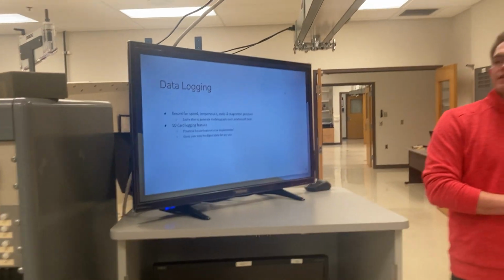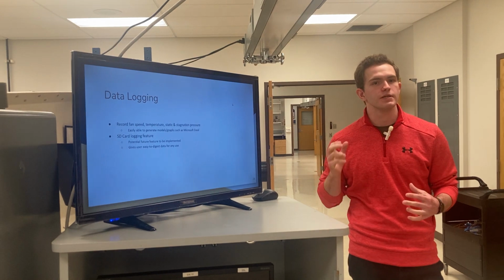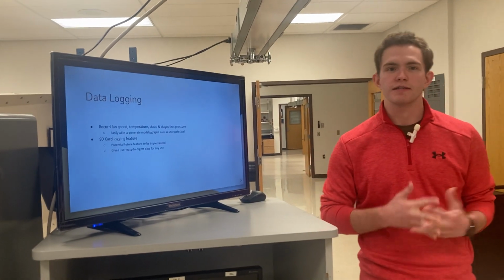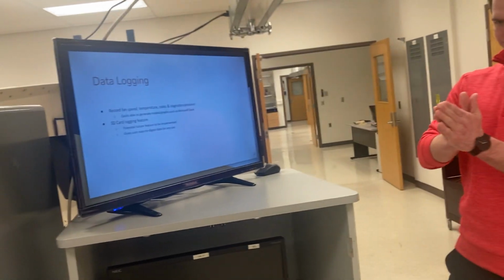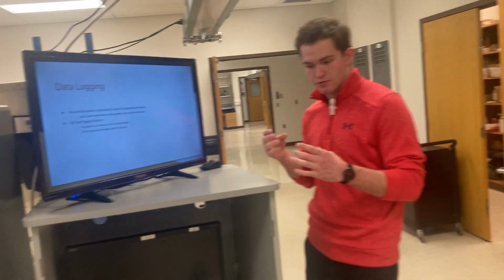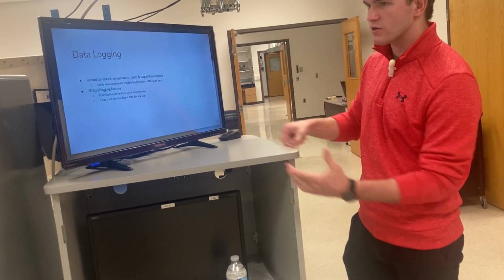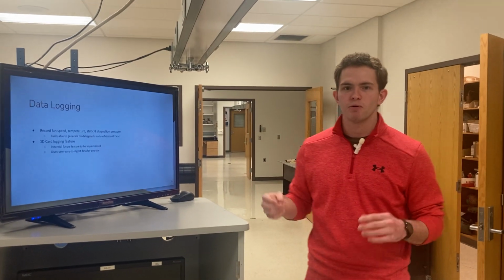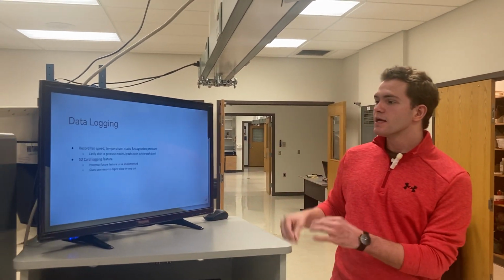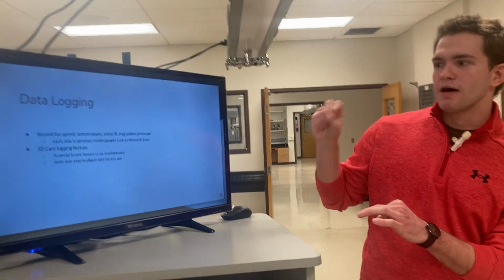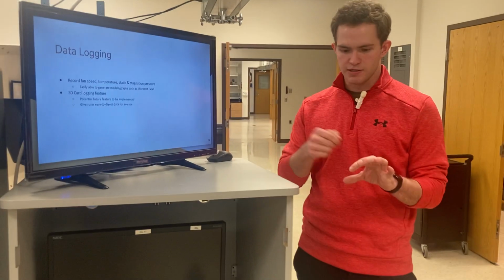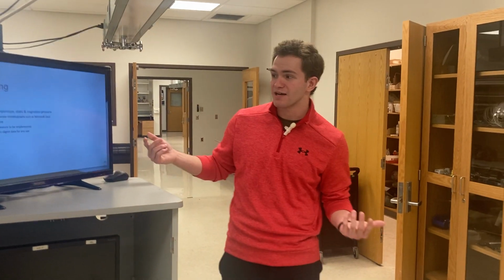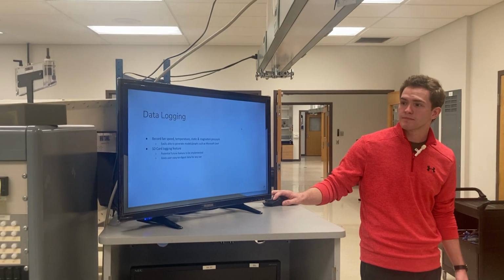And then one future thing that would have been really nice to implement, but I did not have the time to, is the ability to actually log the data. Like the other groups have done, or like we did in our lab, you set the wind tunnel at a specific speed or temperature or whatever parameter you want, and then you write down what you have, which works. You can type that into Excel. But what would have been better, and very easy, was to plug in an SD card. The Arduino spits out all the information that it's currently got, and then when you're done, you take the SD card out and plug it into your computer. But I did not have time. That would be a very easy feature to implement.